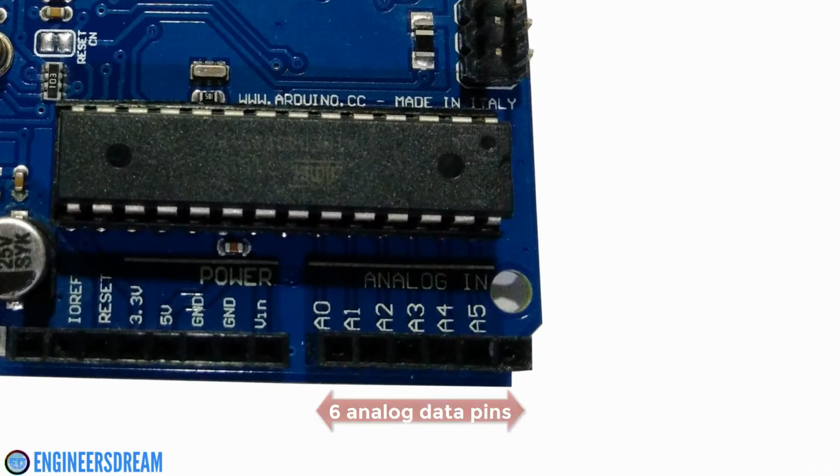An Arduino consists of 6 analog pins which are labeled from A0 to A5, and we can use these pins for connecting analog sensors or analog devices. The analog values that we can read using the analog pins are in the range of 0 to 1023.